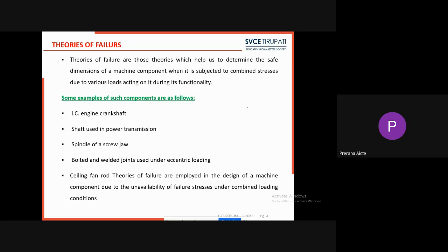Generally, you observe 4 to 5 different types of loads, which can cause deformation, deflection, bending, or stresses. The first load is the tensile load, W_t. One more load is the compressive load. The third one is the shear load. In springs, the bending load also happens, that is W_b, the bending load. And one more, the torsional load, or torsional shear load.